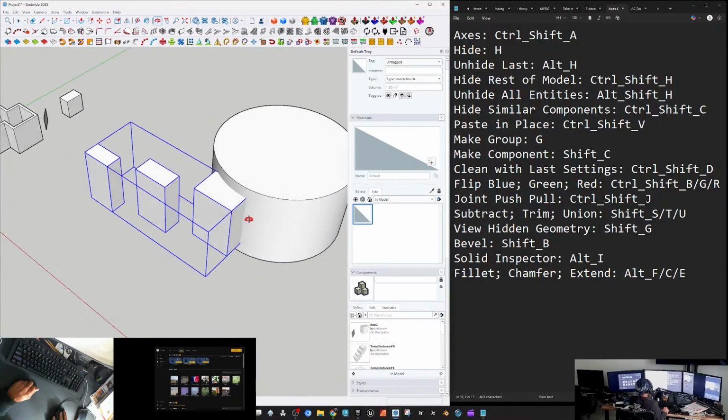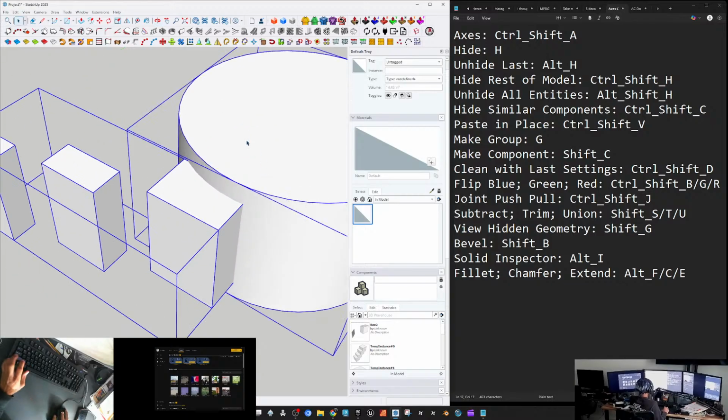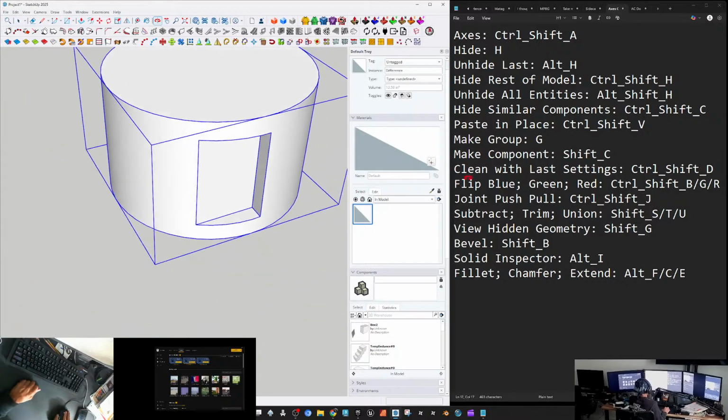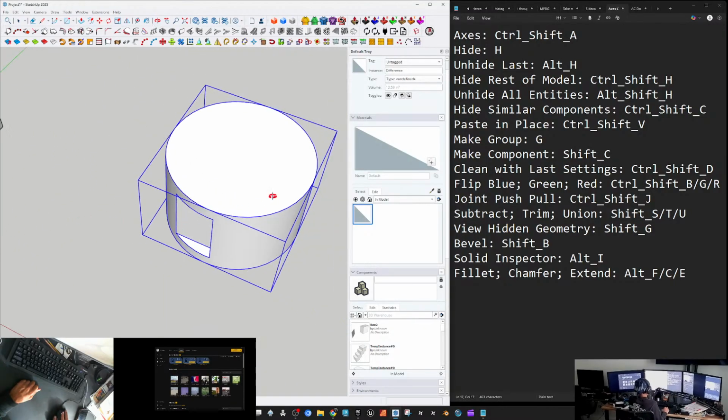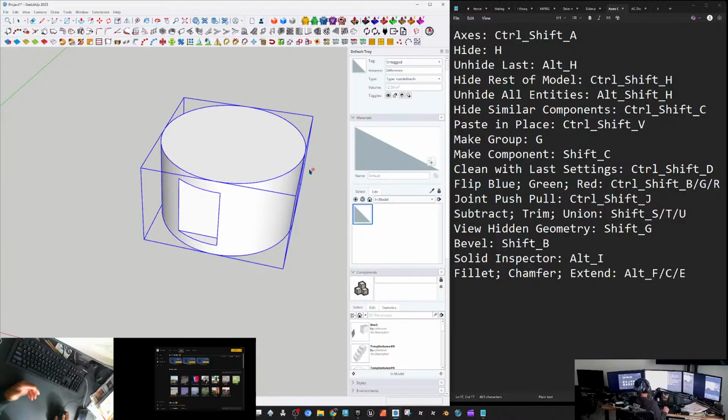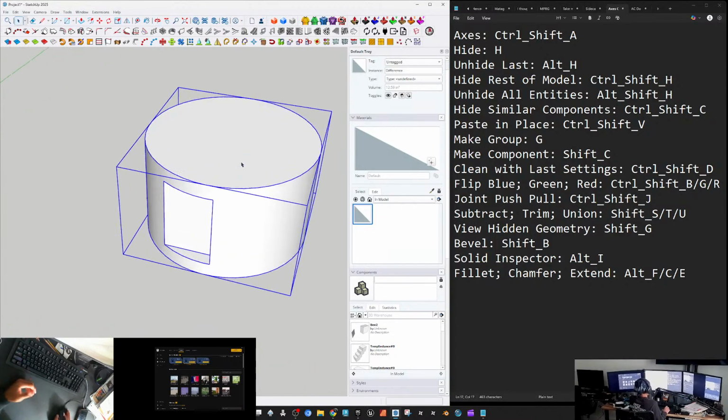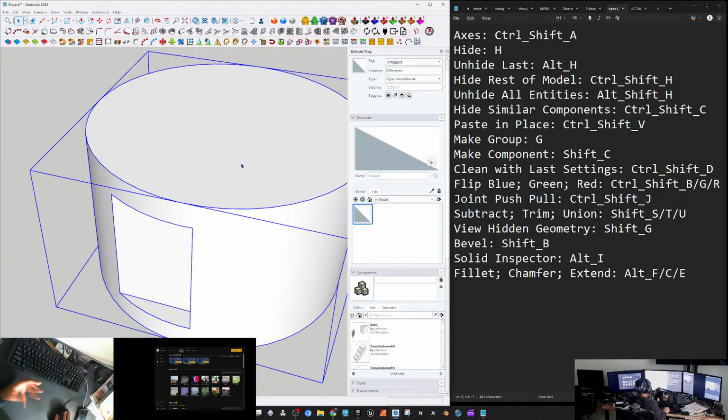So let's click on this other object again, click on my cylinder and Shift S. Now I can use that solid tools operation. So there are various reasons that you might not be able to use some Boolean operations with these solid tools plugins. Usually it narrows down to having holes in your mesh.